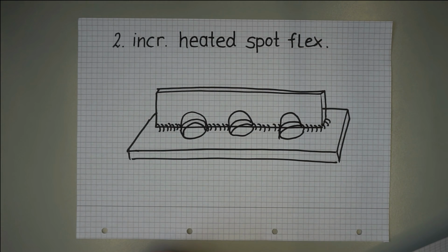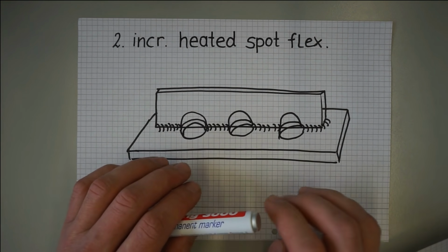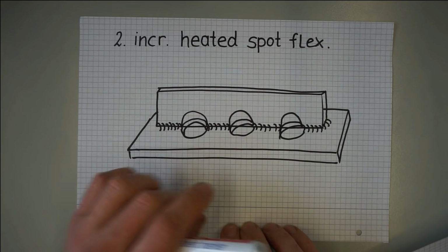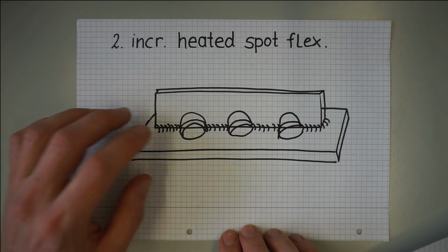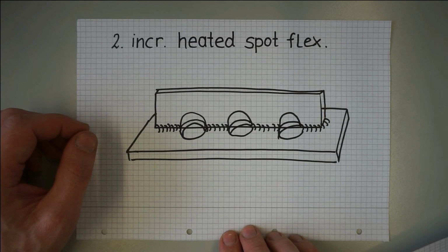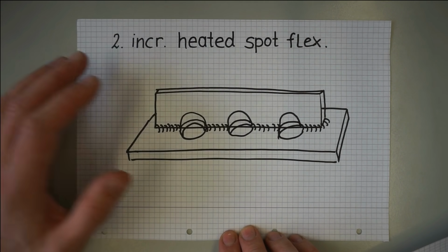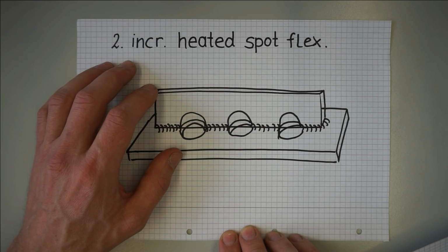Or we can implement this strategy by smartly breaking up our welded design into sub-assemblies, which are finish welded before final welding assembly. Obviously, this strategy to reduce welding distortion can only be implemented in the design stage, so it is more of a method for the expert designer than for the welder. The natural limits here are mostly of a manufacturing nature, for example, avoiding notches, accessibility, minimum wall thicknesses, etc.